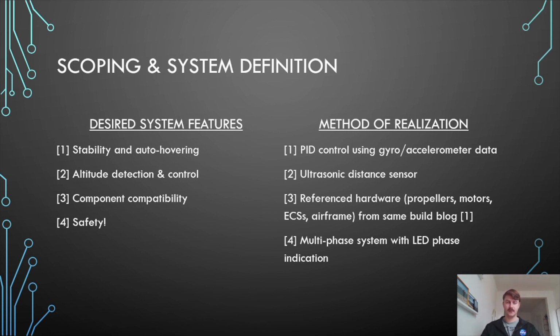To realize that, I used a PID control algorithm that took data from the sensor I had, an IMU, or inertial measurement unit, where the raw data was gyroscope data and accelerometer data. For the height, I used an ultrasonic distance sensor.